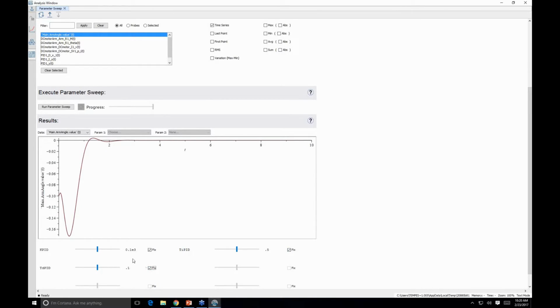So let's keep this setting as the best one. We just keep the one that we set at the beginning: 100 for the KP PID, for the TI PID, sorry, we leave 0.5, and for the TD PID parameter, we leave 0.1.